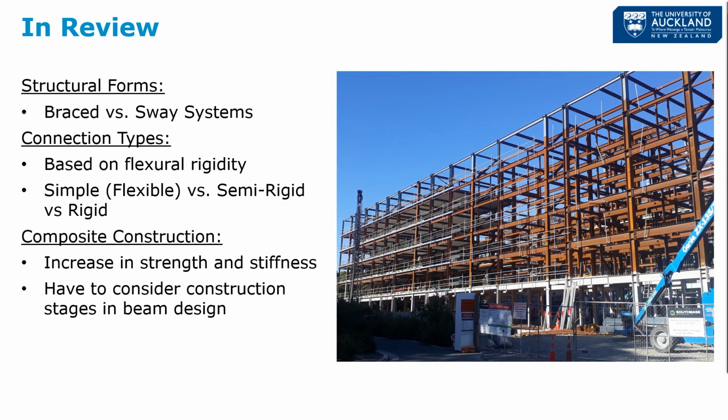And then finally, the thing that we looked at was composite construction and its benefits around an increase in strength and stiffness, but that because of its construction methodology, we do have to consider each of these different stages as we design, to make sure that our loads are considered correctly, as well as the restraints to the ends of the beams and along the length of them.